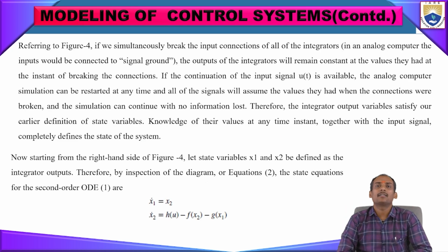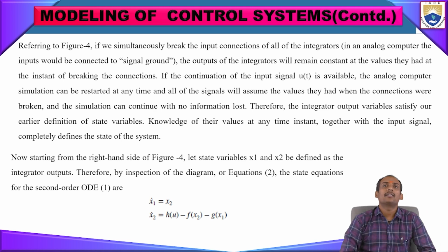So here, if you see that figure, we simultaneously break the input connections of that integrator, so that if an analog input is connected to a single ground, the outputs of that integrator will remain constant at the values they had at the instant of breaking the connections.